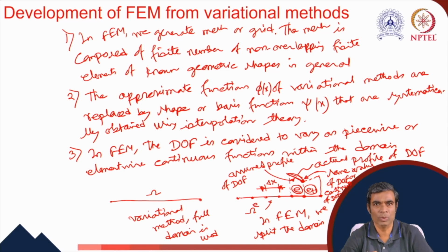It means that we are moving from the continuum approach to finiteness. So the solutions which we calculate by using numerical techniques like finite element, we actually solve for the unknown quantities at selected points. Then the continuum equation is replaced by a large number of algebraic equations, and that large number is a finite number, and because of that we say that we perform discretization. We solve the equation at discrete points. Those points are generated during generation of the mesh.